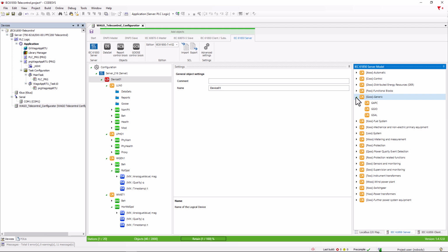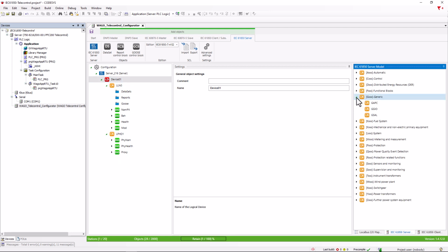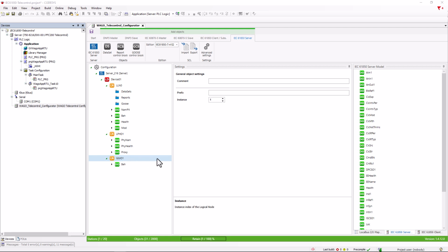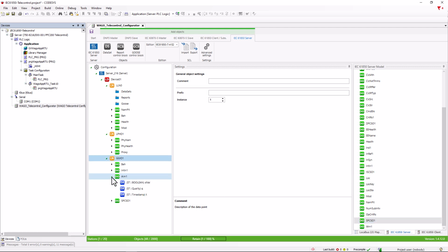The LNGGIO is commonly used in WAGO solutions to convert signals from Modbus to IEC61850 Telecontrol. First, delete the wind turbine and add the LNGGIO to the project. Initially, it only contains the DO behavior, so add an alarm, an integer value and a DO for a single point command. For alarm 1, the typical structure includes the variable, quality information and timestamp.